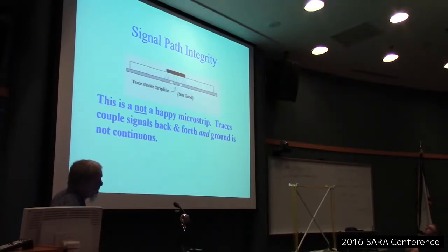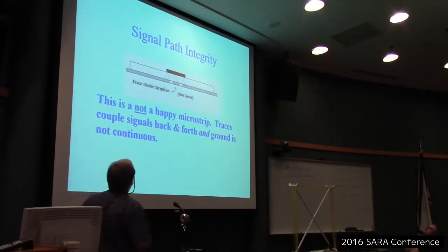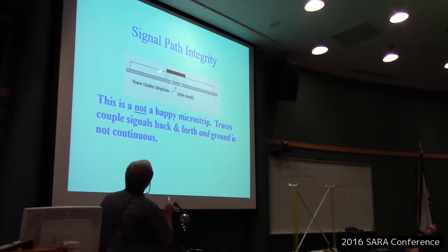Now, this is a particularly interesting microstrip. I've actually seen that problem show up several times in the past, not just on this one product that was in trouble there. Somebody needed to run a power trace there, and somehow the power trace ran for a couple inches right smack under the microstrip. So it's done a couple of things to the microstrip that's not good.